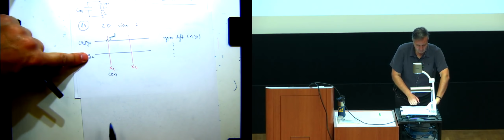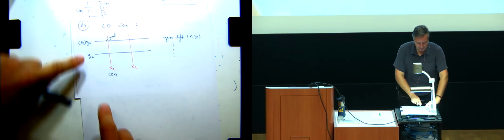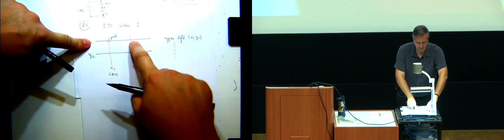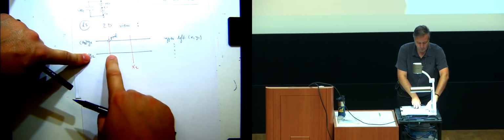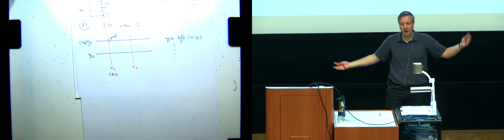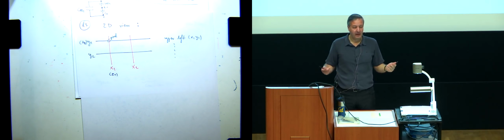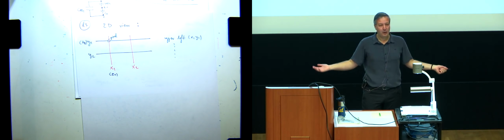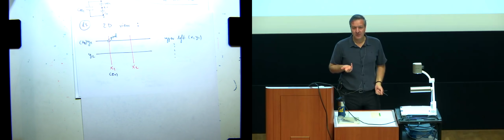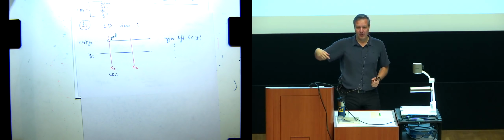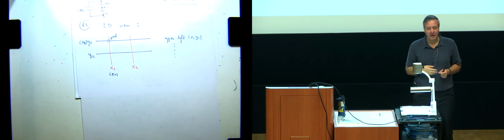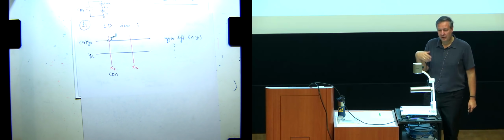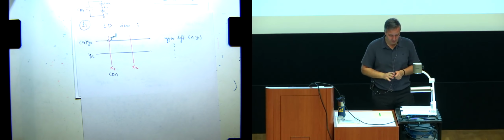If I put some measurement circuit between y1 and x1, I will measure this pixel. If I put it between x2 and y1, I will measure that pixel. x1 and y2, I will measure this pixel, and so on. I can measure every single pixel in the whole screen. And that's indeed what the circuitry does in your phone. It's just super fast. It does this at nanosecond levels, and your finger moves way, way slower. So your phone can interrogate millions of pixels before you even move your finger, so it can sense the movement of the pen, of the finger, of things like that.